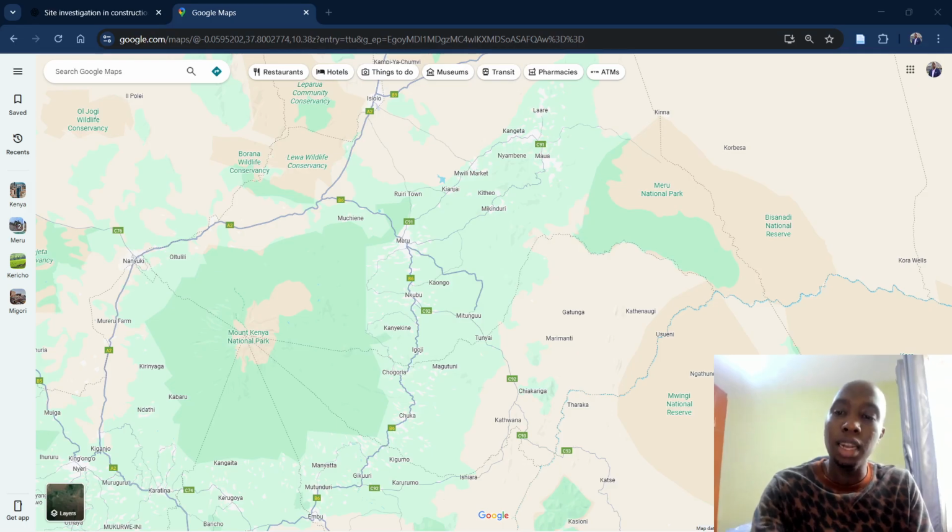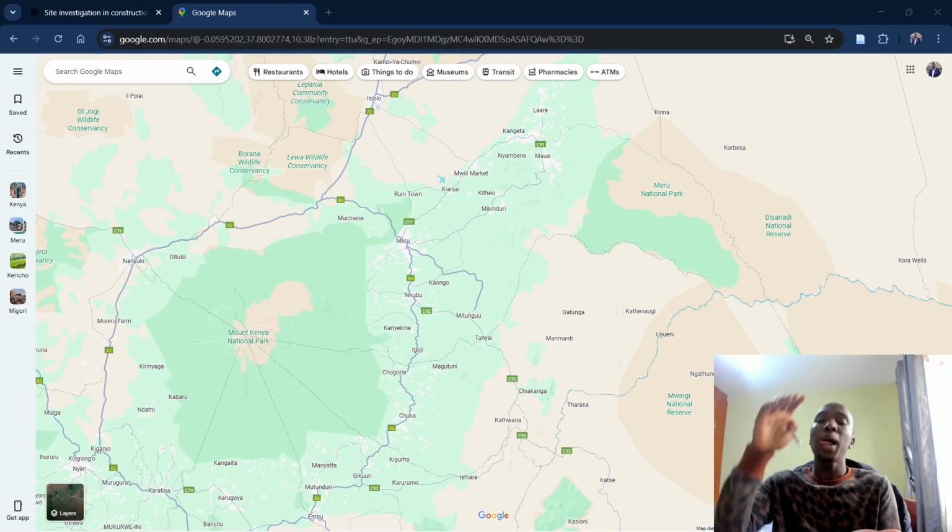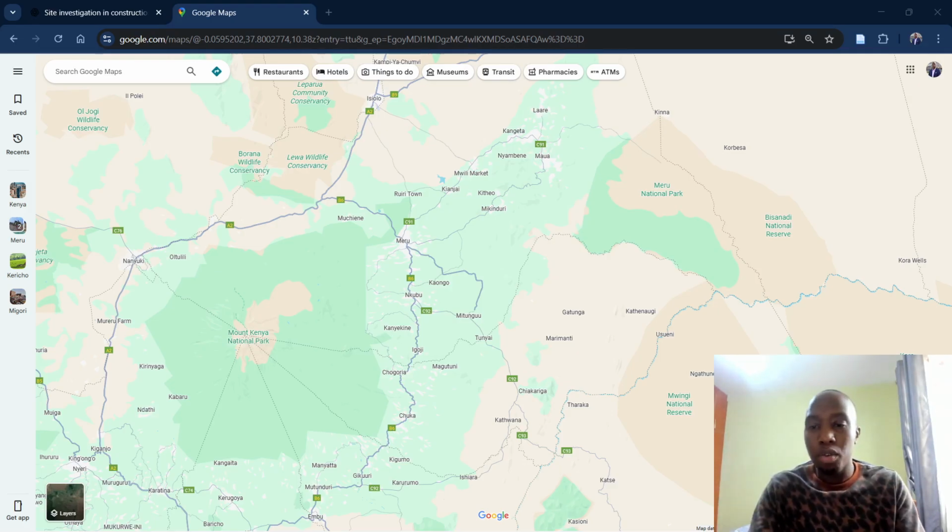This is the third step, soil exploration, where you have what you call trial pits. We are going to see these, don't worry. Trial pits, boreholes, test pits to examine soil layers and soil properties. So you go and dig, and you see what the orientation is. For instance, I remember you guys learning about the soil profile. We have the topsoil.